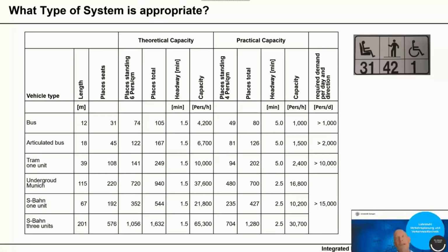But if you look at places like Bogota, where they have, I don't know, 5 million, 8 million inhabitants, you notice this system is great that they have it, but in the end, the capacity is not enough for a city of that size. So somewhere around that 10,000, that is a value where you can start thinking of installing a rail-based system.